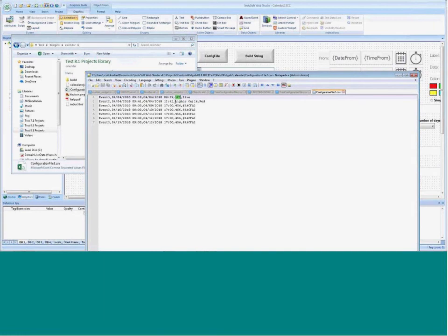In this case, I configured two pieces of data between commas, separated by the pipe character, the vertical line on your keyboard. You could separate them with a semicolon, whatever the case. I'm going to show you how I then use a built-in scripting function with InduSoft to parse those two pieces of data out of that single payload.